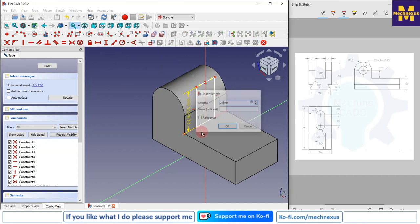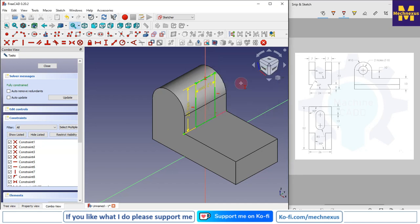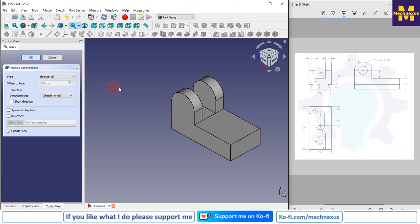So we will give approximately 25 mm, and our total width of the part is 26, and here it is 7 and 7, 14. So 26 minus 14, so I will directly give 26 minus 14, so this is 12. Now I will close it and I will make extrude cut, and I will say through all and say OK.